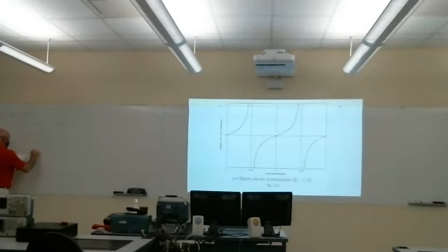We saw last time that with our voltage reflection coefficient, the voltage is equal to V0, the amplitude of the right propagating wave, and then the ratio of the amplitude of the left propagating wave to V0 is gamma, our voltage reflection coefficient.